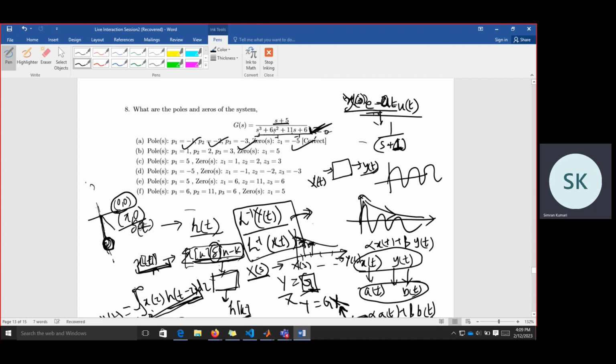If this system is perturbed, suppose we give a force, I have mentioned this in the lecture also, but suppose we give a sudden force. So how will it evolve? Because there is no input, just a perturbation. This is kind of an impulse, a sudden input. So its initial condition is this now, and it will try to move like this. If there is damping, or we can say a resistive force, then it will go and settle to equilibrium.